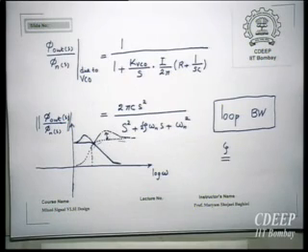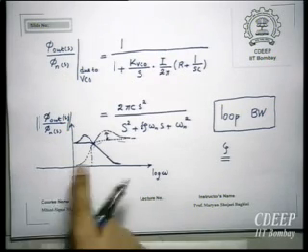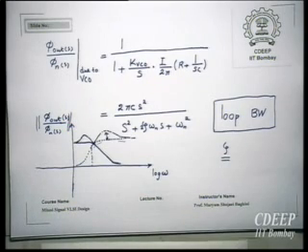And therefore, usually when you design a PLL, in fact, this is one of the things we do. We always look at what the jitter peaking performance will be. We have to simulate that and then make sure that the phase noise that we get will be below some value.